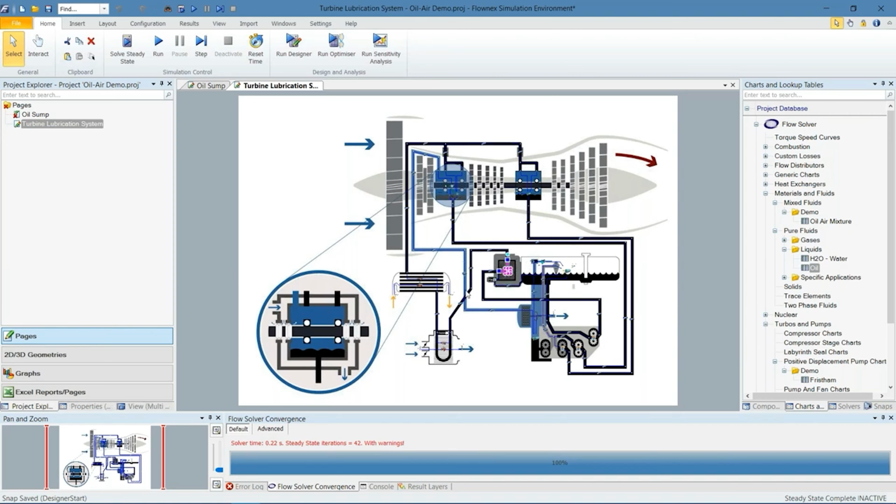We then have the oil flowing through a heat exchanger where the oil is cooled by air. We then have another heat exchanger where the oil is cooled by fuel. Basically, heat is transferred from the oil into the fuel to warm the fuel and cool the oil. That oil then flows up through piping, through some last chance strainers, and then into the bearing sumps.